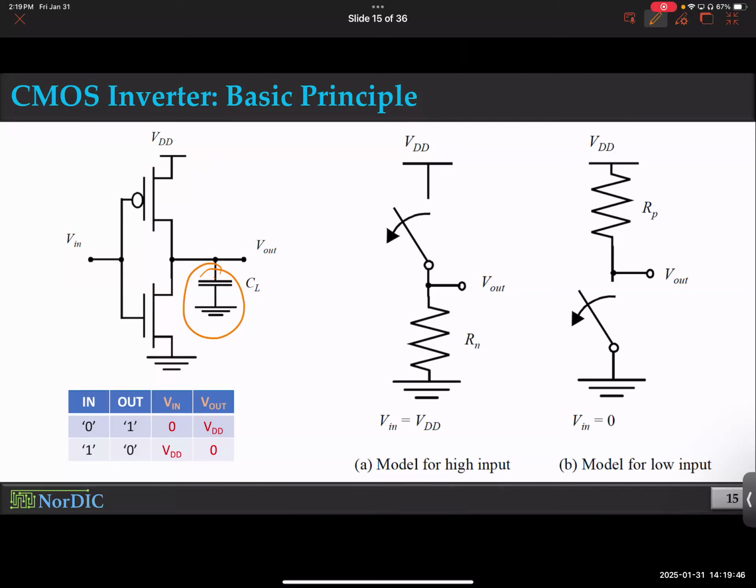That doesn't mean we connect a capacitor with NMOS and PMOS. You might be wondering, oh, that means an inverter has three components: an NMOS, a PMOS, and a capacitor. We do not connect that capacitor. You get it for free. And there was 335 again. There was another lecture where MOSFET is full of capacitance. They're everywhere. So when you connect two MOSFETs together, their drain capacitors come together and make an equivalent load capacitor. So you get it for free. So when I say we create a strong one, that means we can charge up the capacitor from VDD.